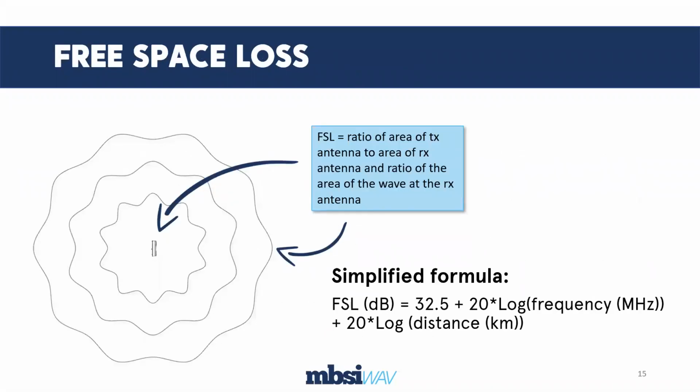I'll show you how to do that. And we can come up with a maximum range that we can deploy CPE in to meet those characteristics. Now, this is free space loss. It doesn't take terrain into account. It doesn't take trees and clutter or anything else into account. And we'll talk about that in a minute. But this is the farthest that you can go when you have line of sight between your two antennas.